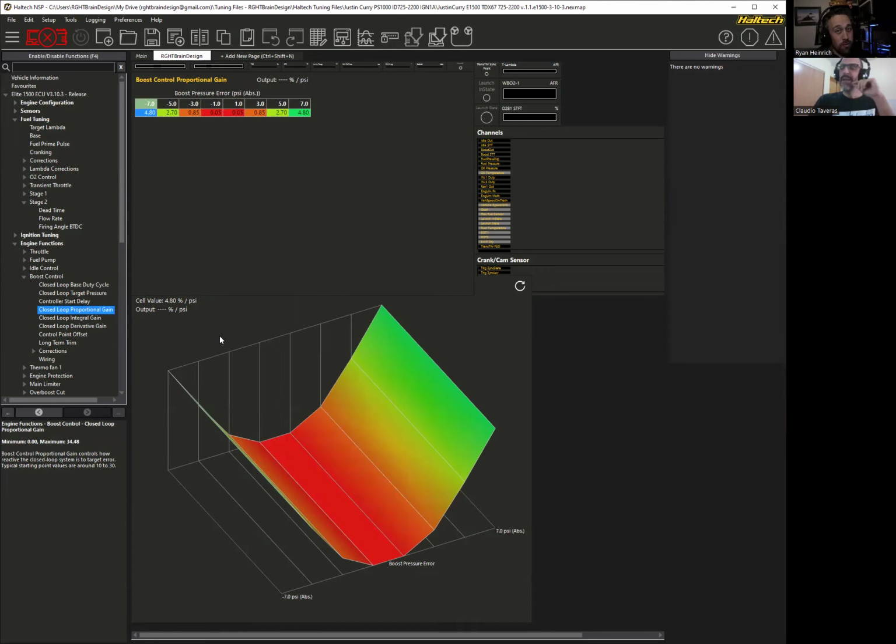Speaking of erratic, the three-port MAC solenoid, hot day, cold day, different boost offsets. Normally, when characterized, it can be about a PSI and a half of little oscillation of just normal stuff. You could try to characterize it perfectly for every air temperature, but that does not account for heat soak for most models. On a four-port MAC solenoid, and why I don't have one for my car, I actually have two three-ports, that's going to have almost a 3 to 4 PSI offset of consistency.